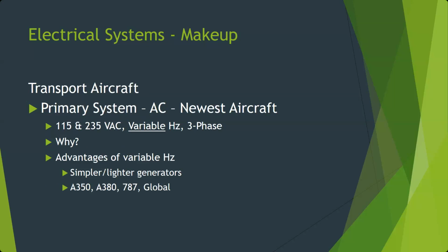You know, maybe you need 100 of those chips in the whole airplane. And altogether, those 100 chips weigh a couple pounds. It's still a lot less than one 80-pound constant speed drive. So for the components that need a fixed frequency, we put in something that can take in a wild frequency and puts out a constant frequency and does it in a solid state manner rather than using a mechanical drive.